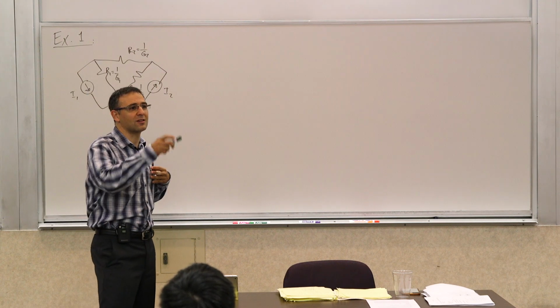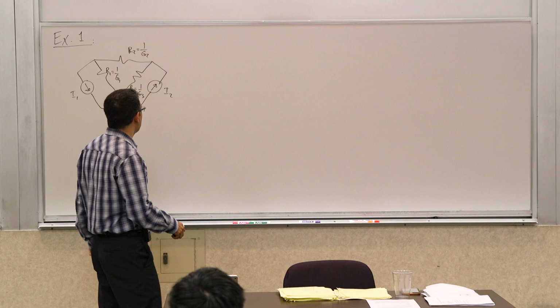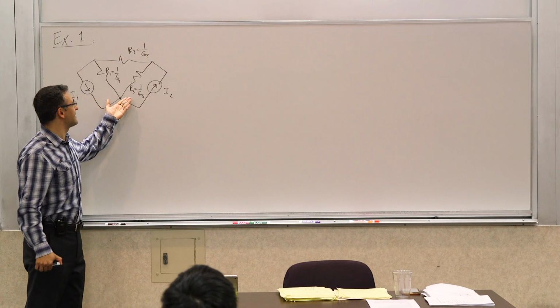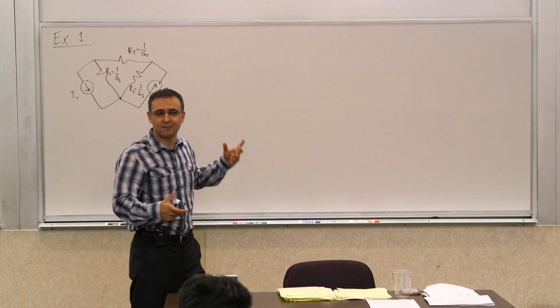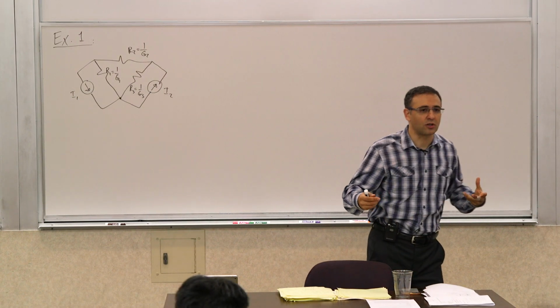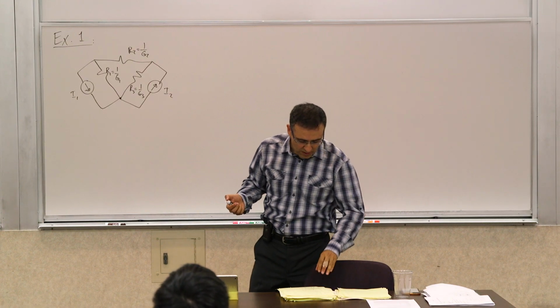Because sometimes you don't want to constantly write 1 over R1, 1 over R2, or 1 over G2. And you will see, in fact, in nodal analysis, it's easier to deal with the conductances than resistors, because it's based on some parallel notion of stimuli. So what do we do?